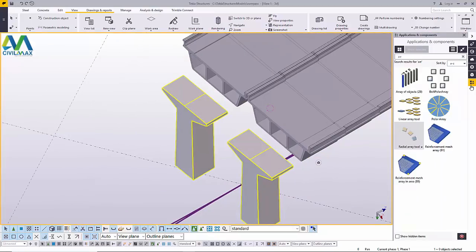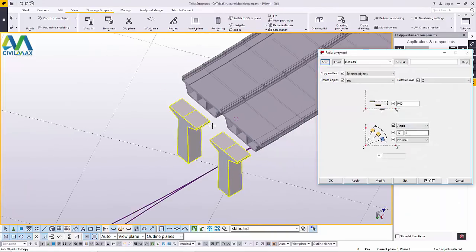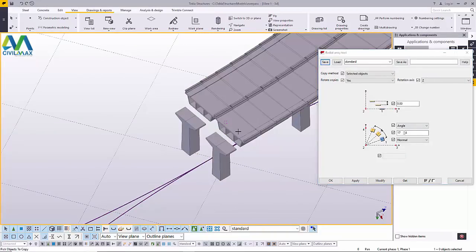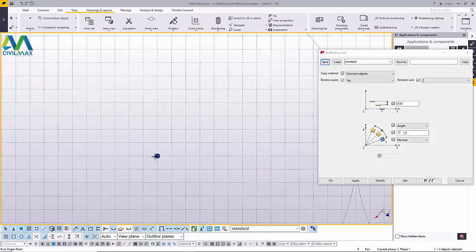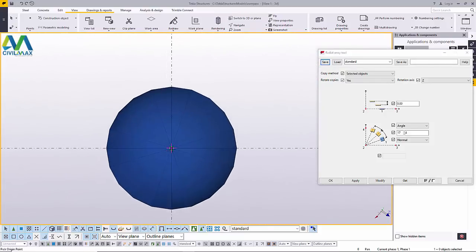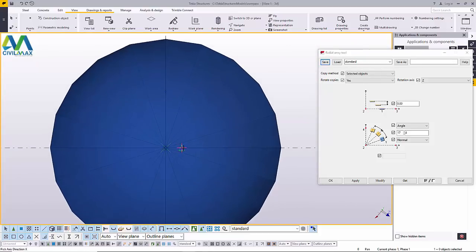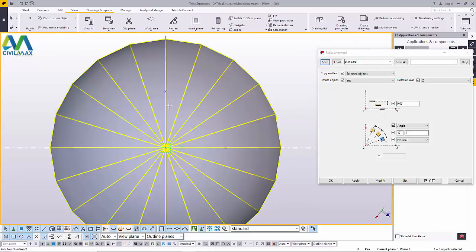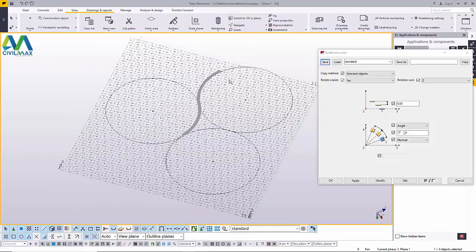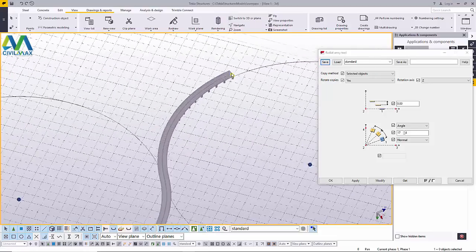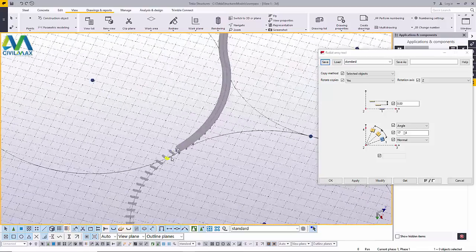Now this will take us back to our Radial Tool, and we'll deactivate that assembly and pick on that, press Ctrl and pick on that, and press our middle button on the mouse and switch back to our midpoint here, and we'll snap right here and define our x-axis, which will be that, and our y-axis will be that. Press our middle button on the mouse and switch back where we were and check whether everything has been populated perfectly.